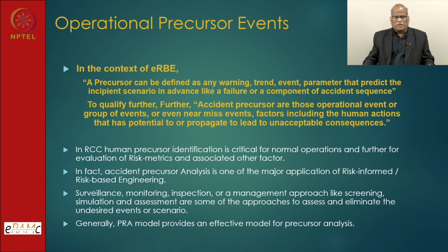Now, there is also operational precursor analysis. What we are saying here is that failures happen later on, and in fact, it is almost similar to prognostics. But symptoms are available. So some precursor studies, like some smell is coming in some room, is it an electrical failure, or some vibration level increasing? Is it a precursor to a pump failure or any other failure? So this precursor study forms a very important part in PHM also, and as such at the plant administrative level also, or technical level also.